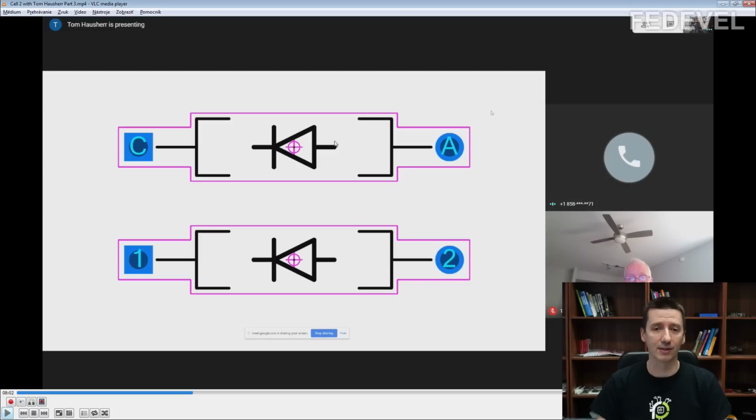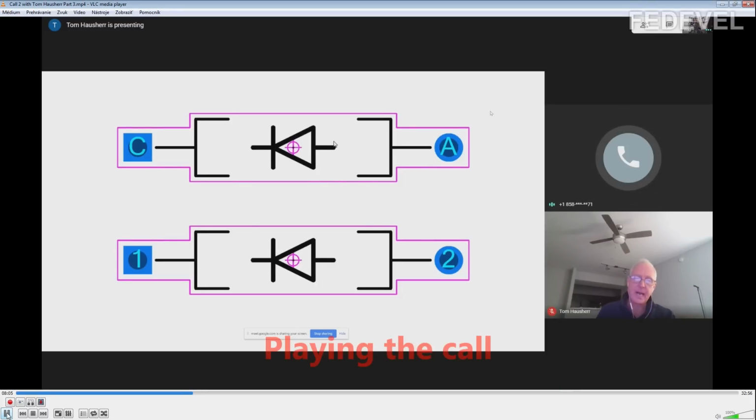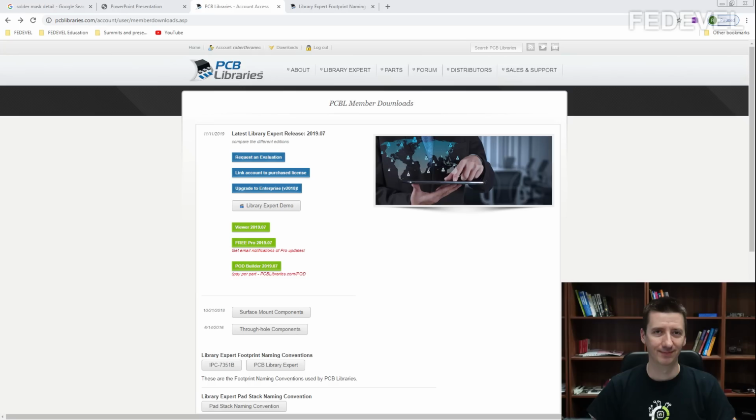But here is something from our discussion about diode pin marking or pin naming. For the polarity markings, we have a question about anode and cathode and diodes and pin 1 and pin 2. For cathode and anode, it's better to use the letters C and A, because if you use pin 1 and pin 2, the schematic symbol will have pin 1 and pin 2. And what happens if the engineer puts pin 1 as the anode on the schematic symbol? Then they give you a net list, and you have pin 1 as a cathode on your footprint. Then the manufacturer, everybody does their job and everybody does fine. You get the boards back and they don't work, because the engineer had pin 1 on the anode, the designer had pin 1 on the cathode, and it's called a screw up. So in order to not screw it up, you just use A and C, and it's impossible to screw up. Impossible.